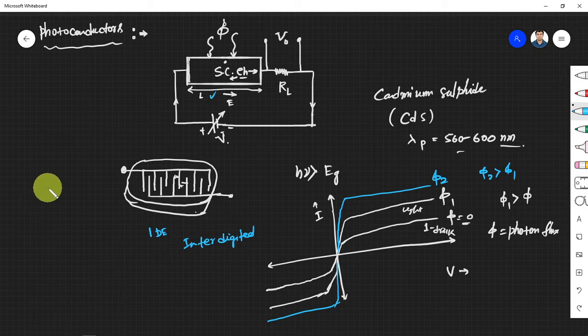Yes, so that's how the field is more. So the field is more, and also the transit time of the carrier, if you see, the electron had to travel all the way across the device, right? Now the electron can be collected at a very nearby electrode. So the transit time is also reduced drastically for the carriers.